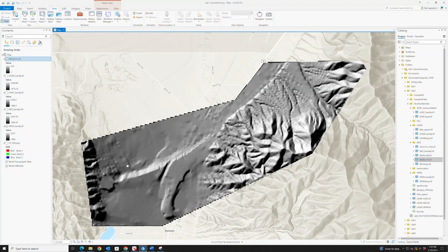So there's our national elevation data hillshade model. And so it has a 315-degree sun angle, which is from the northwest. So we can see that any slopes that were facing the northwest are illuminated, and ones that are facing the southeast are in shadow. So it's modeling shadows across a landscape to show us topography. So hillshade is a very valuable visualization product.